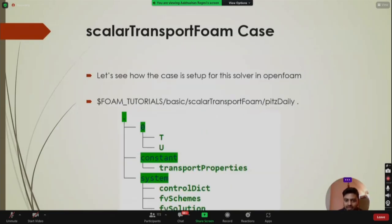So we'll see how the case is set up in OpenFOAM for this solver. We only have one case, pitzDaily, in the tutorials, and the folder is present in this directory inside the tutorials: basic, scalarTransportFoam, pitzDaily. As we already know, an OpenFOAM case contains three subfolders: zero, constant, and system. Inside the zero folder, we have to define the initial and boundary conditions.